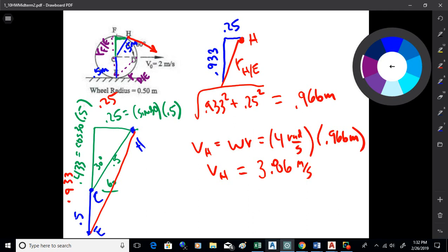The key fact, and this is something especially if you're a mechanical engineer, because you'll be doing more of this stuff, kind of put this one back in the file somewhere: you can analyze wheels that way if they roll without slipping. They're just like they're hinged at the bottom for that one instant. Just for the instant you're analyzing it, you can do it that way if you want. So we got any other questions on that? All right, so that's that one.